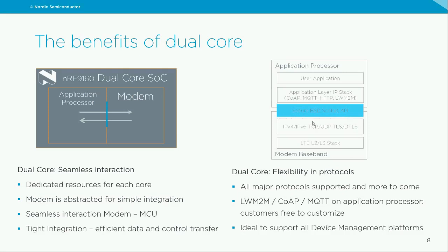Here you also see that for communication, all the stacks up to IP, TCP, and TLS and DTLS are running inside the modem, while all the higher level stacks, all the middleware that you need to connect, is running on the application side.